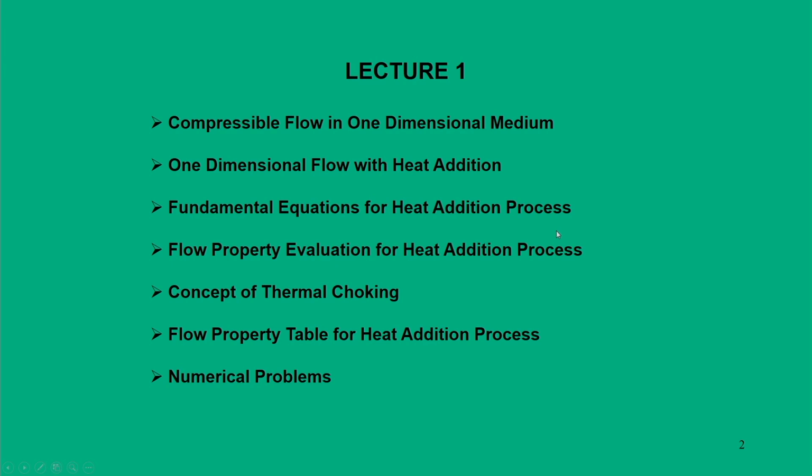we will deal with compressible flow with heat addition, and to be very specific, the entire analysis will be done in a one dimensional medium. Like in other situations, we will also derive the fundamental equations for the heat addition process, and the flow property evaluations when heat is added to the compressible flow. Then we will introduce the concept of thermal choking.